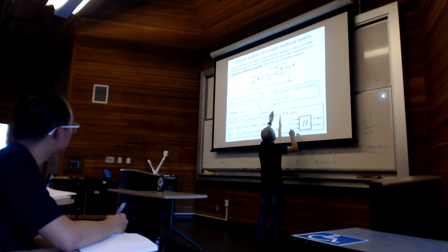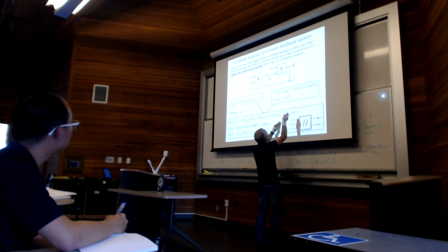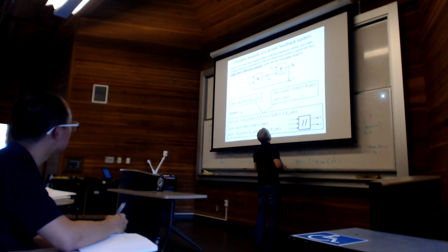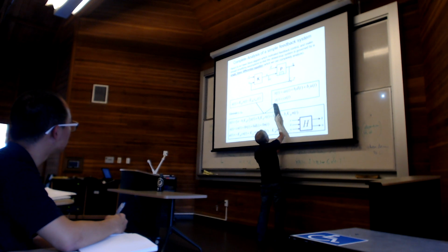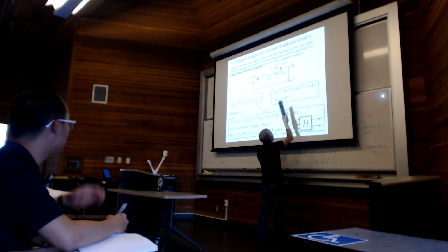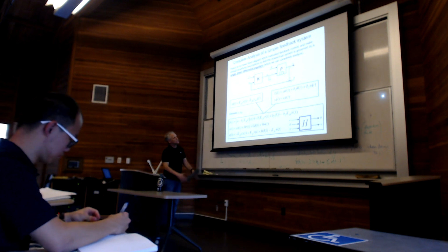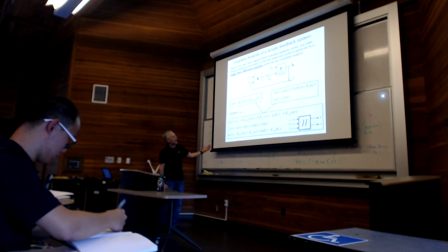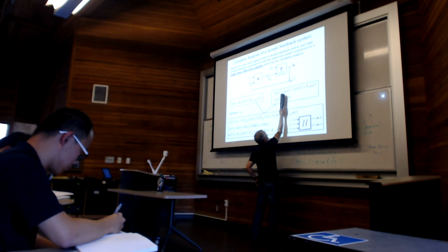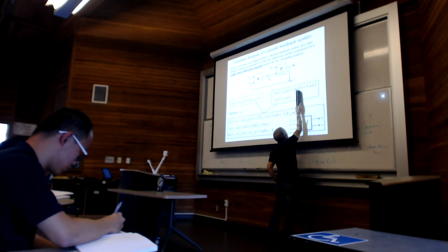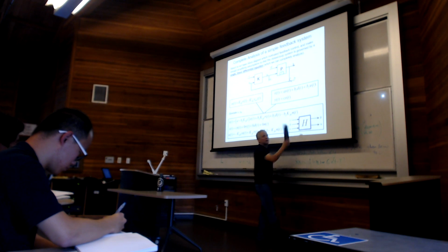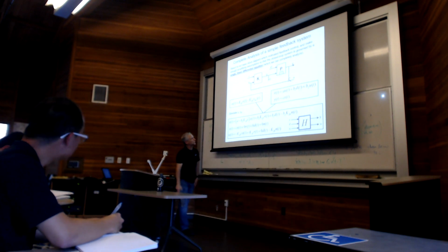So the process is our standard: x dot is some ax plus b1 times the disturbance plus b2 times the control. And then y will just be some c times x. So the output is just some consequence of the state. It's very much like our rocket: theta dot was theta plus u minus d, and y was theta. So that would be handled by this equation.